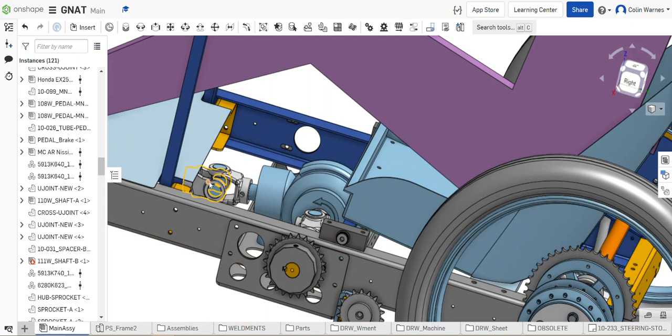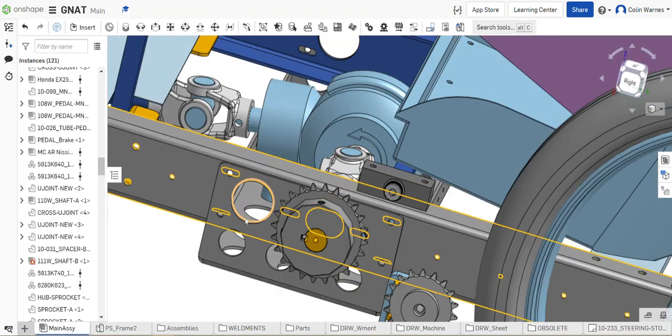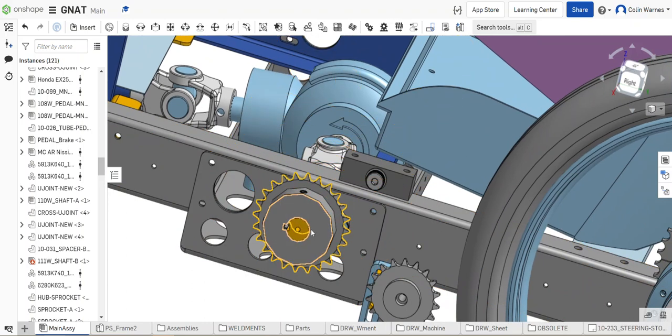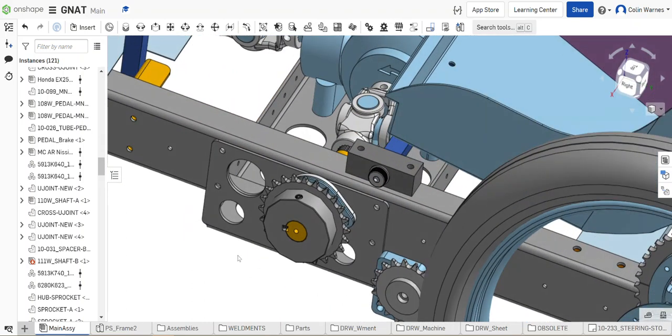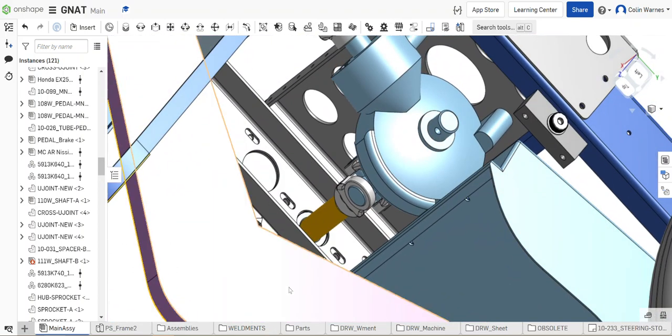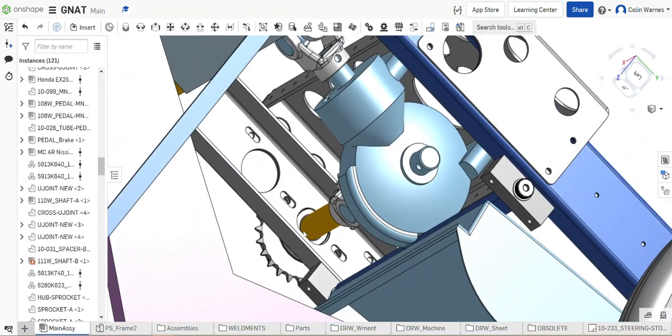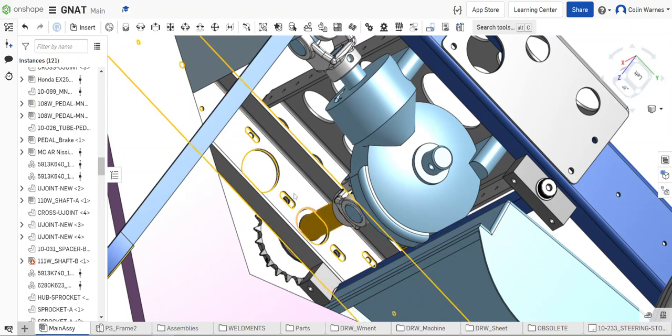Because anytime you're designing parts from things that exist, and you're trying to reverse engineer them, it's really hard to get them dead nuts on perfect with tape measures and calipers. You're going to be off somewhere. So I planned a little bit of tolerance in there to allow this assembly to shift forward or backwards. And the whole bearing assembly, you can see in there as well, is designed to move as a unit with this cross member assembly.